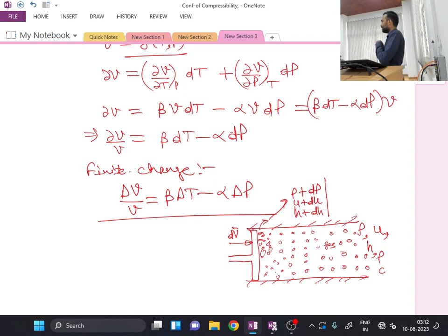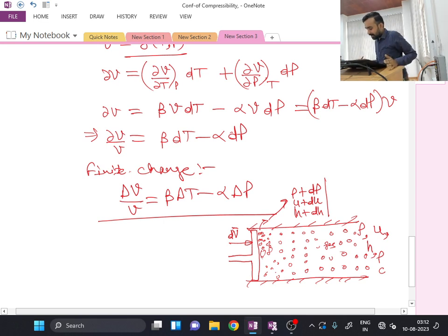So you know that speed of sound in solids where molecules are closely spaced is more in comparison to liquids, and then it is least in case of gases. Okay, so what I am trying to say is that near the piston I have slightly compressed the molecules. Okay, so as molecules have become slightly compressed, here speed of sound will also become C plus dC, slightly larger than the speed of sound in the other region.